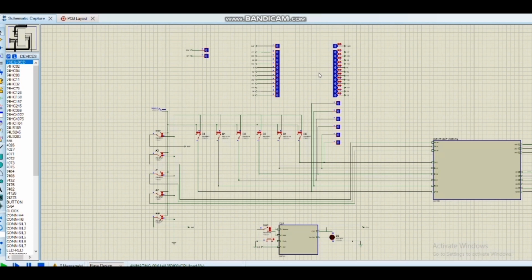And also, if we want to write some values in our RAM, we make the r/w, or read/write, to 0, and if we want to extract that data out, we have to make the r/w 1. All right, so in order to save those data, we will first use the first three RAM locations, let's say 000, 001, and 010.